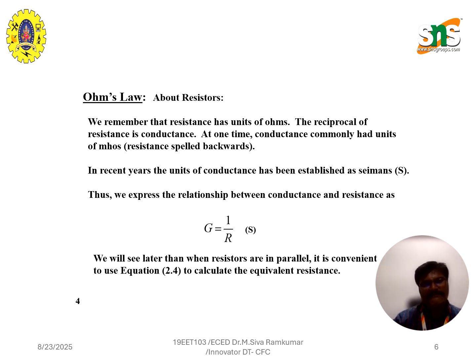Conductance is the reciprocal of resistance. It is termed G. The mathematical representation is G equal to 1 by R. Its SI unit is Siemens, represented as capital S, which replaced the earlier informal unit called mho, literally ohm spelled backwards. This concept becomes extremely useful when analyzing parallel circuits, where conductance values add more conveniently than resistances.